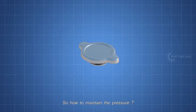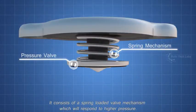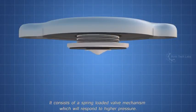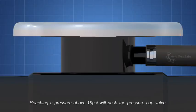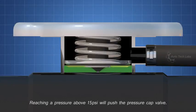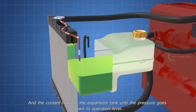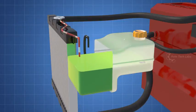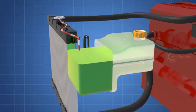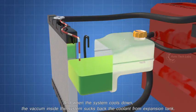Heating liquid inside a closed system always builds up pressure. So, how to maintain the pressure? Here comes the role of the radiator pressure cap. It consists of a spring-loaded valve mechanism, which will respond to higher pressure. Reaching a pressure above 15 psi will push the pressure cap valve, and the coolant flows to the expansion tank until the pressure goes down to operating level. And when the system cools down, the vacuum inside the system sucks back the coolant from the expansion tank.